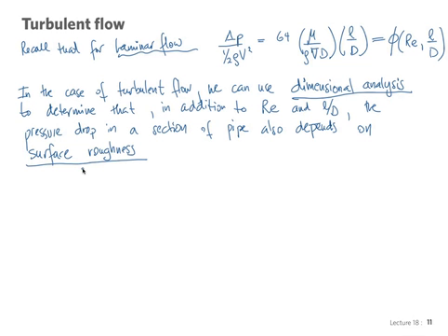For laminar flow, it goes into parabolic. You see that there isn't really a thin boundary layer. The viscous effects are equally felt all across the diameter of the pipe. And so the little kinks in the surface don't really matter. If I want to give sort of a hand-waving explanation of this, it can be worked out more rigorously, but we are saying that in terms of the turbulent case, we have to introduce, in addition, the effect of the roughness of the pipe.